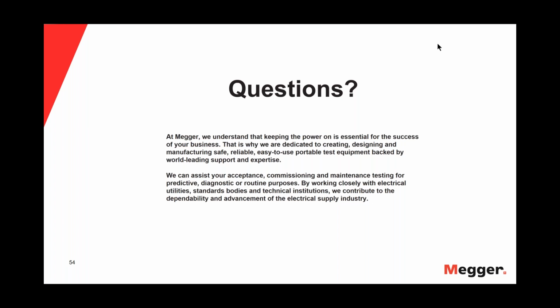Normally, first of all, if you did this test, I hope you didn't do it on a solid dielectric cable, because you shouldn't do a DC hipot test on a solid dielectric cable. It might have been on a paper cable. And if you did it on a paper cable, then most likely, if you have a higher leakage current, that means you have moisture in the cable, and that creates that higher leakage current.